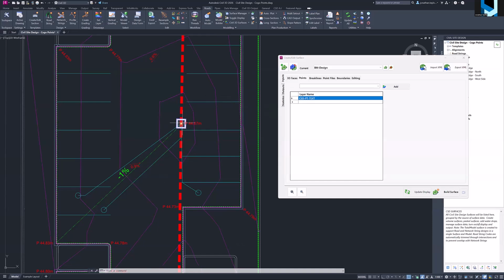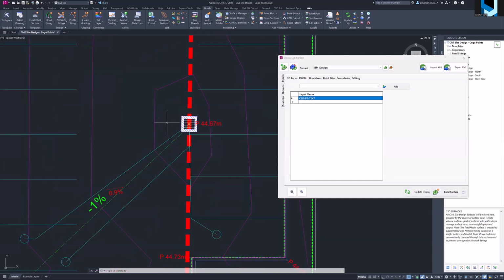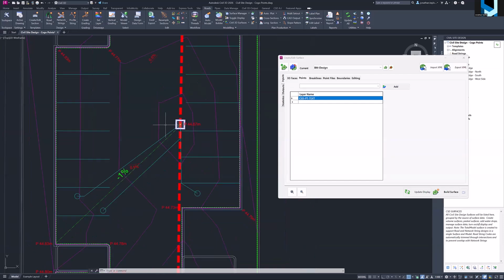That works great, but when you try and introduce something on the surface which is literally just a point, there's nothing underneath it. There's no subgrade defined on that point. So, as Todd's alluded to, you end up potentially creating a rectangular grading stream that just has a zero width, 150 mil or whatever it happens to be, subgrade for it to model to, which is a bit messy, but creates a point inside the subgrade model to triangulate to. So yeah. Cool.